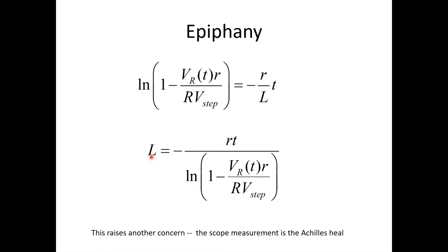Okay, and the interesting thing is we're going to measure the resistance of the inductor with an Agilent precision LCR meter. So we're going to have a very high, better than 50 parts per million, measurement of the resistance of the inductor. We're going to have better than 50 parts per million measurements of the ramp resistor.